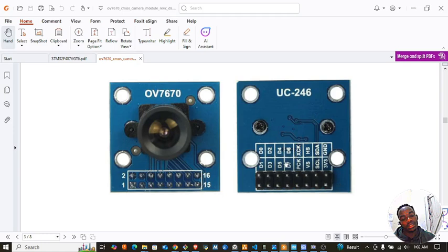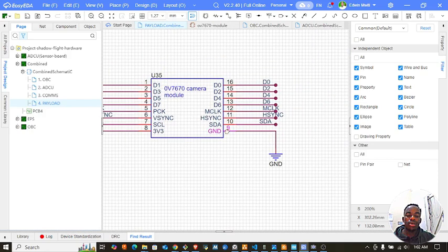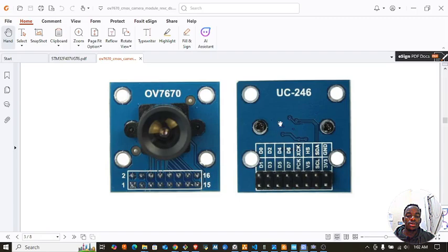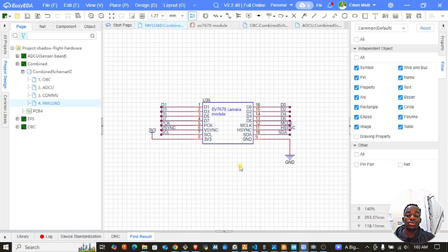And reset, there should be reset somewhere. Funny, there's no reset. Anyway, we'll check with the module you buy whether there's reset or not. But these are 16 pins. So I think everything else is handled correctly on the module. We'll recheck. I can't assume that.